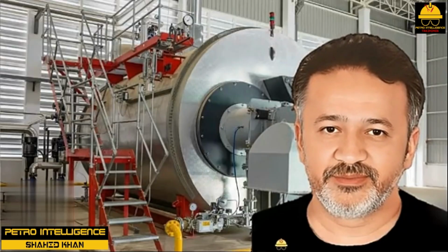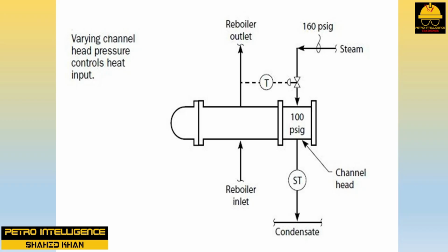Steam flow control. The flow of steam to a reboiler can be controlled by using a control valve on either the 1) steam inlet line or the 2) condensate outlet line. The picture shows a control valve on the steam inlet line. The rate of steam flow to the reboiler is not really controlled directly, however, by this control valve. The actual rate of steam flow to the reboiler is controlled by the rate of condensation of the steam inside the tubes. The faster the steam condenses, the faster it flows into the channel head. The function of the control valve is to reduce the steam pressure in the channel head of the reboiler.